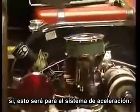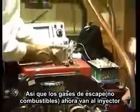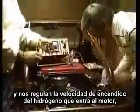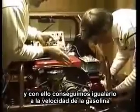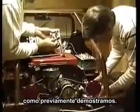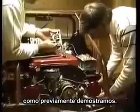Okay. Now this is going to be our feedback, our exhaust feedback control, which sits right in here. And that'll regulate the exhaust gases going back into the injectors, which in turn, here's our injectors. And so our exhaust gases are going to go back into the injector, and that'll regulate the burn rate of the hydrogen going into the engine, so we'll adjust the hydrogen burn rate to co-equal the gasoline, as we've demonstrated previously.